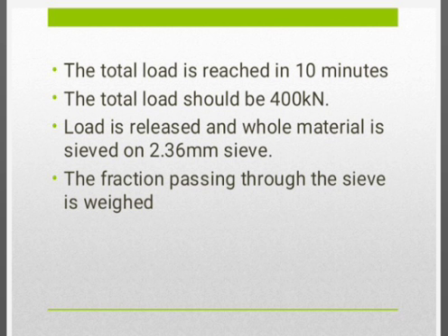The surface of the aggregate is carefully leveled. After that, a plunger of diameter 150 mm is inserted on it, so that it rests horizontally between the platens of the testing machine. It is in a horizontal position. Apply the load at uniform rate.